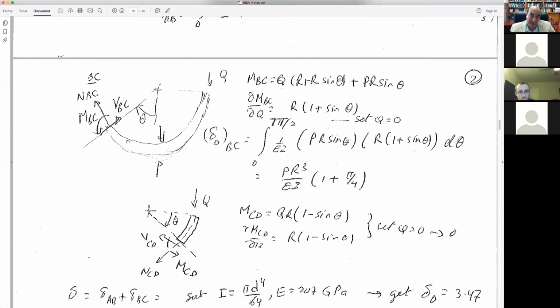So instead of dx, it will be R d theta. The integral becomes from linear to a theta integral, from 0 to pi over 2. These kinds of problems a lot of times pop out sine squared and cosine squared, or sine cosine, something like that, because you have a moment and you have its derivative. So you get sine from here, cosine from there. You get these kinds of weird functions, so we have to be careful. Usually in the exam we don't have time to apply the sine squared or cosine squared formula, so we just give you the result for specific integrations of these functions that you can use in the solution.